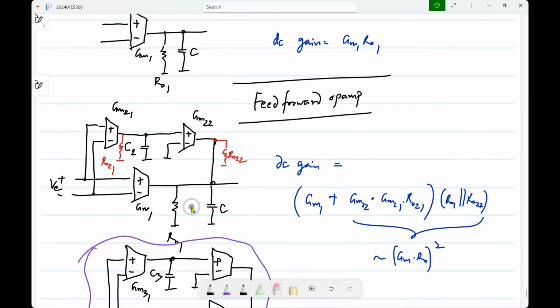Okay. Again, keep in mind, how did we get this? We made a feedback loop using this op amp. We applied DC, let it reach steady state, and after that we basically let the second loop operate and reduce the error further. Okay. So given that explanation, what can you say about this path?